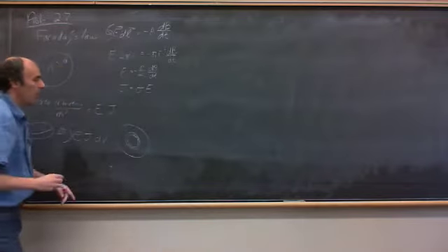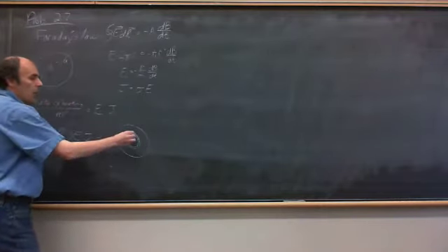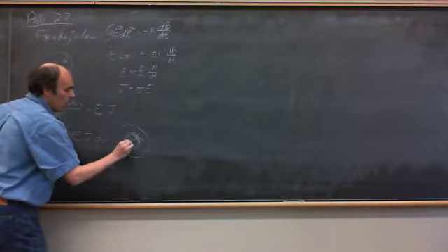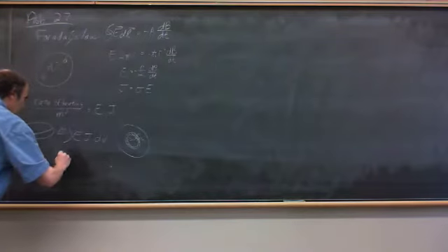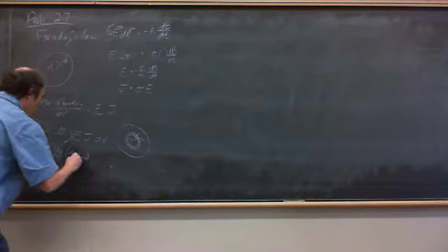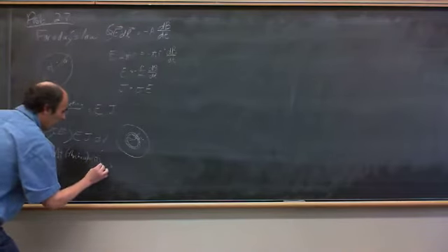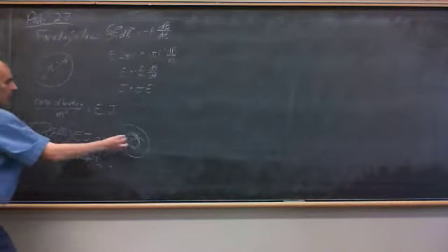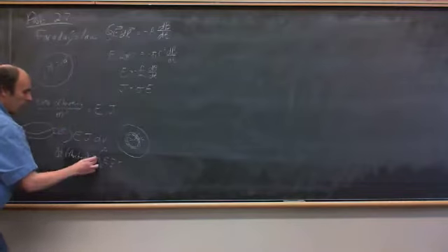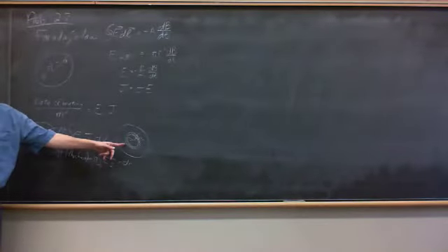The electric fields depend only on r. So if you integrate in little strips like this, each has a thickness dr and a radius r. So dV becomes the thickness of the entire electrode times 2 pi integral from 0 out to a of E, J, and this is r. There's the 2 pi r dr. So you end up doing this integral.